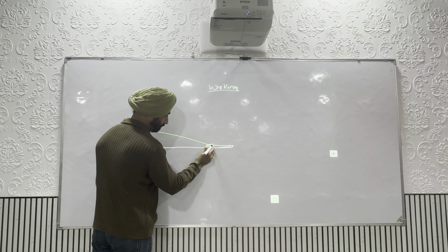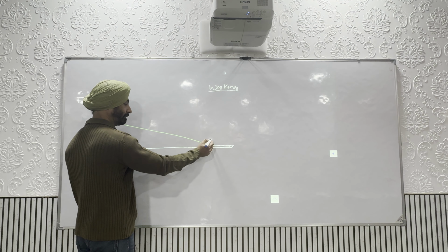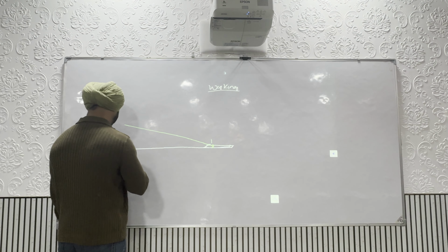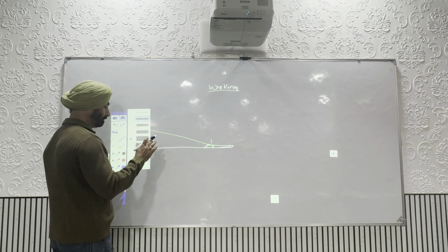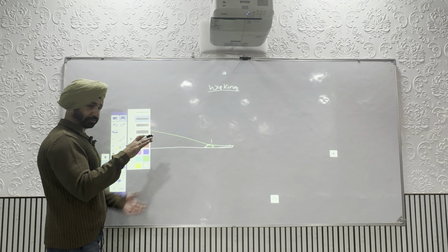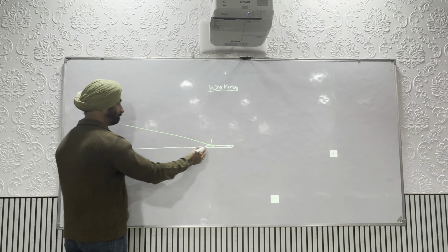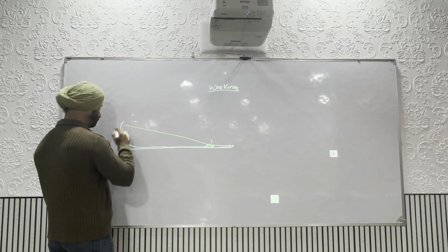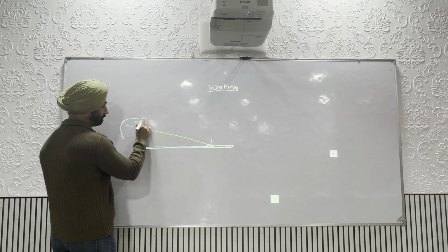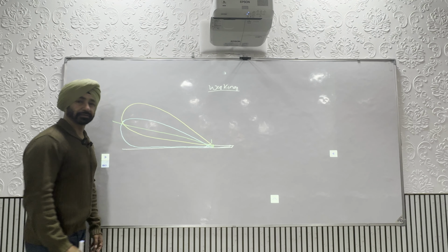Next to your touchdown point, you have that antenna which is transmitting in the approach direction. It transmits two lobes in the approach direction, one above the other. The bottom one, an easy way to remember, is blue, and the top one is yellow.